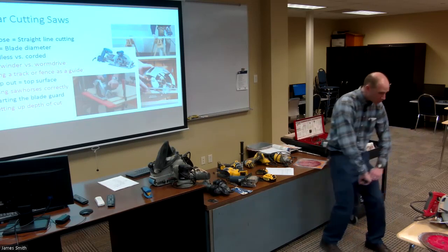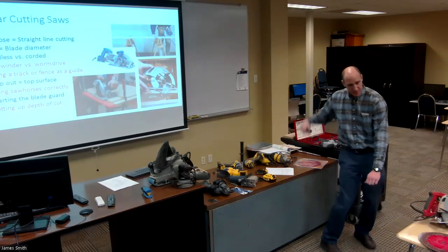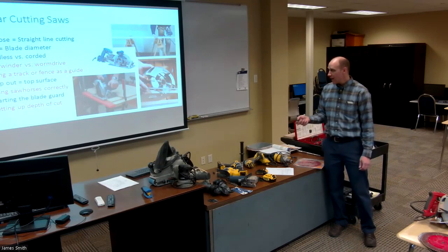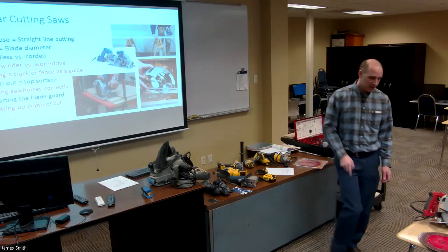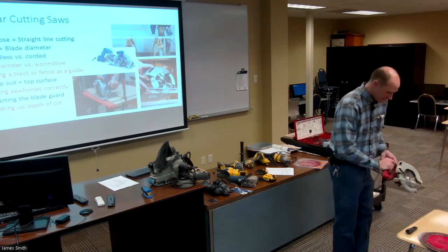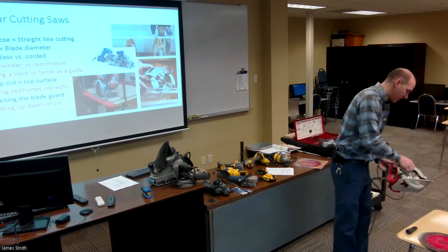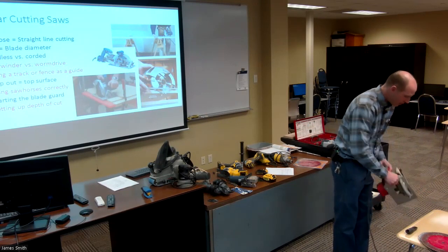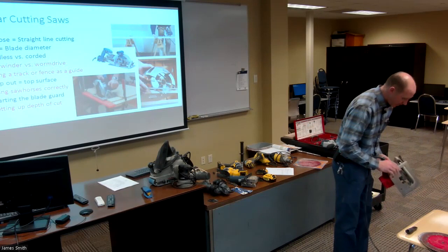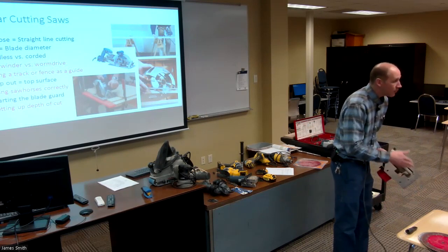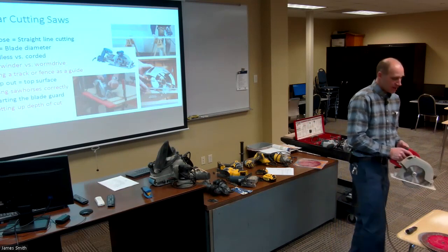Bam, it's going to drop, it's going to pinch the blade, and it's going to kick your saw back, and that's no bueno. Okay. The other thing too is oftentimes doesn't get done, but you really should, is just making sure that you're setting the blades. You don't have a ton of blade exposed. You can just quick flip that and then adjust your blade height, or how far deep your blade projects through past the base and then go ahead and cut that.